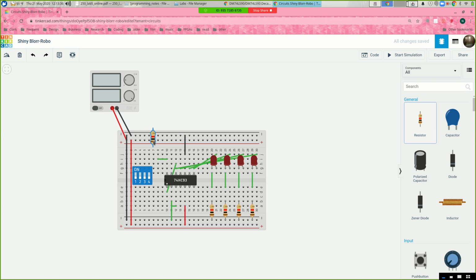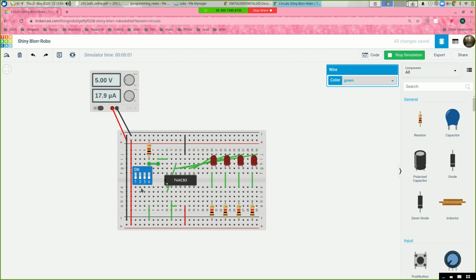So we'll put a resistor to 5 volts. We'll connect this side to ground. And we'll take pin 14 from that point. So flipping this switch should do the same thing as having our clock toggle. Okay, so let's see what this does.